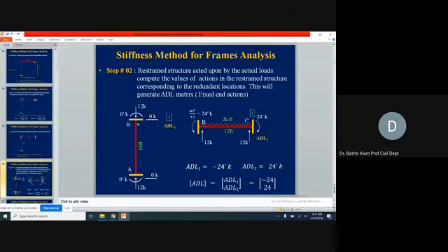Now remember, if there was some shear force at B in the horizontal direction, we did not stop the horizontal sliding here. So what will happen from this joint B, in the opposite direction, it will shift to joint B of the BC member, and for the BC member, it is going to be balanced by this joint C force. So here you will have the opposite reaction, whatever you have on this B. The member has to be in equilibrium. So maybe in the next problem, we are going to have this kind of situation.